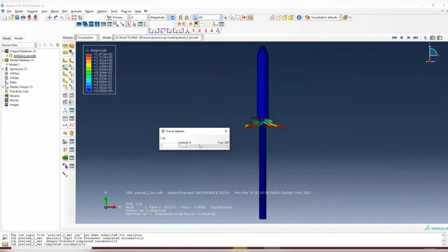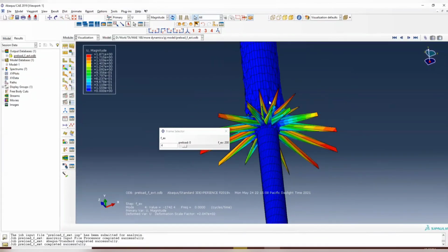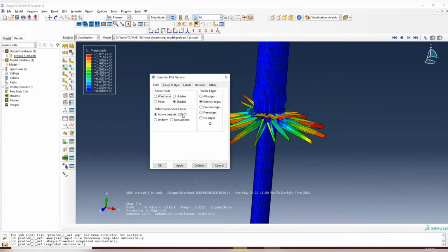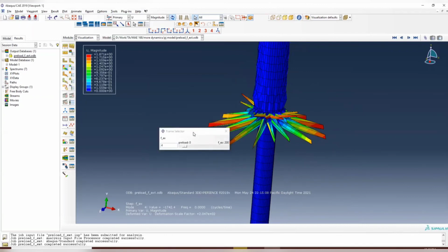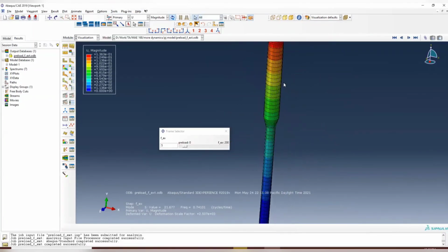You can see the natural frequencies here. These are some buckling modes. Although it looks like a pretty crazy shape, this is after normalization, so you will see it's very large. It's increased by 204 times of the actual displacement. That's why it looks pretty crazy here. But it doesn't matter. This is buckling mode, and this is not the mode that we need to pay attention to.